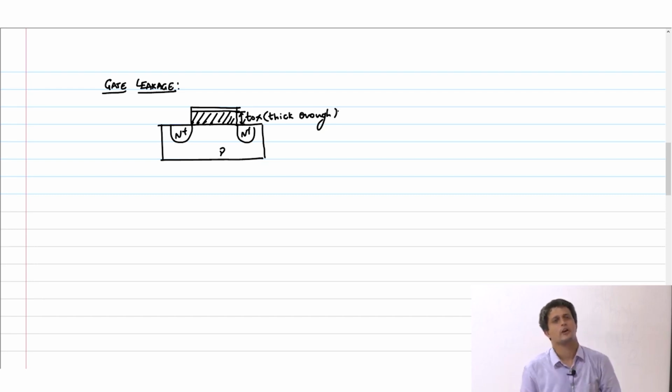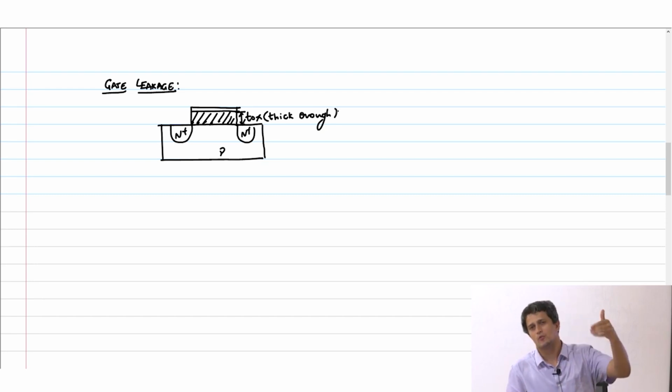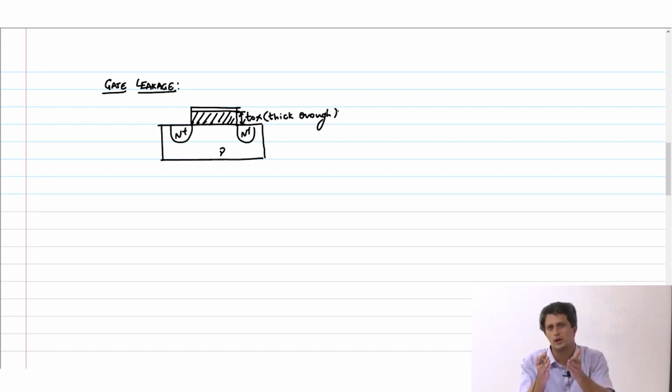until about 45 nanometer. What does that mean? It means from 180 nanometer, 130 nanometer, 90 nanometer, 65, the transistor started shrinking. Why did they shrink it? So that you gain power, you gain area, you gain delay, everything, right? By bringing the drain and source closer together, we would achieve greater speeds. With that, you also got lesser area. You also got lesser power, and of course, why lesser power? Because if I bring these two junctions close by, I have to reduce my supply voltage also. Otherwise, the junction will break down. In all this, you were actually able to gain a significant amount.